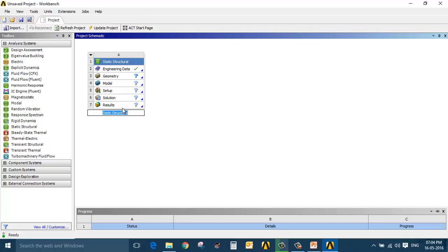So before doing the impact analysis or torsional or bump analysis or rollover analysis, my suggestion is to first perform a free run where we check the connectivity of my entire roll cage members. Because if my roll cage members are not connected, then the force transfer or the constraints transfer will not be proper.